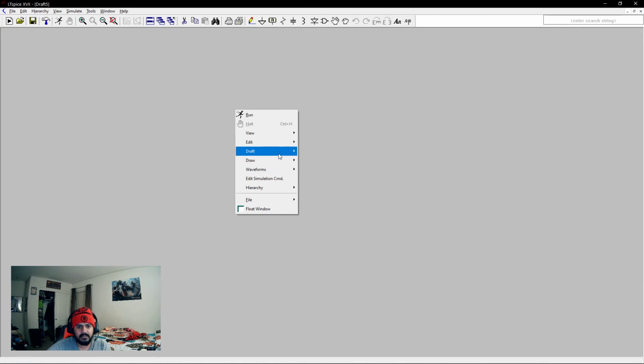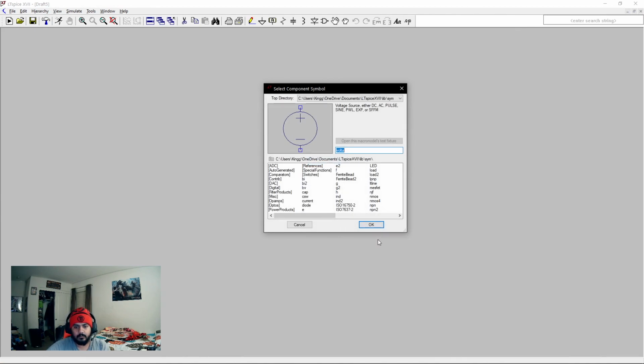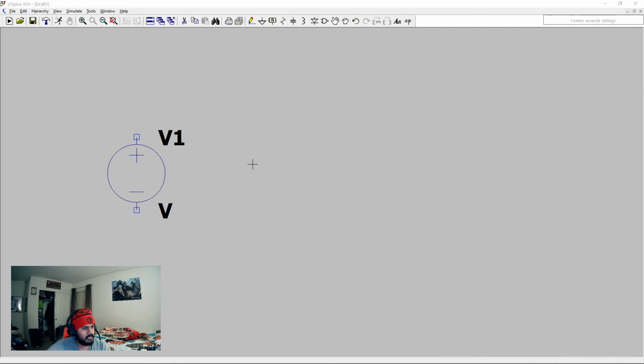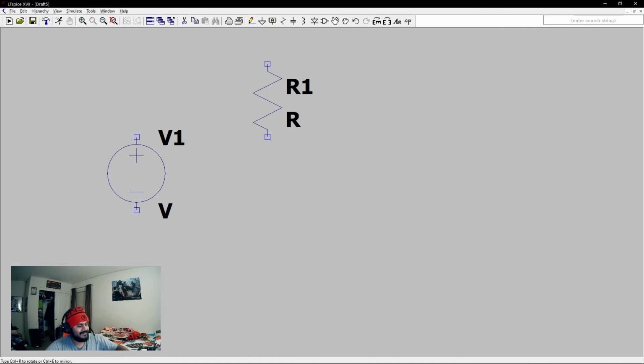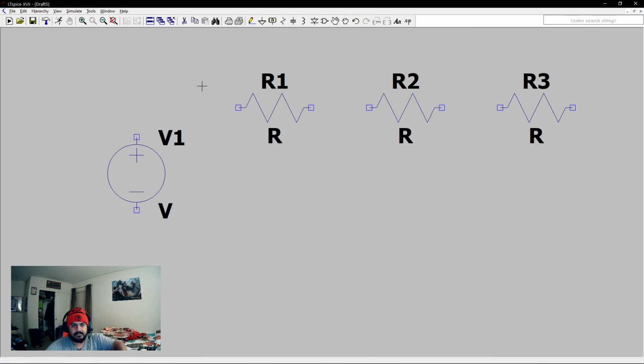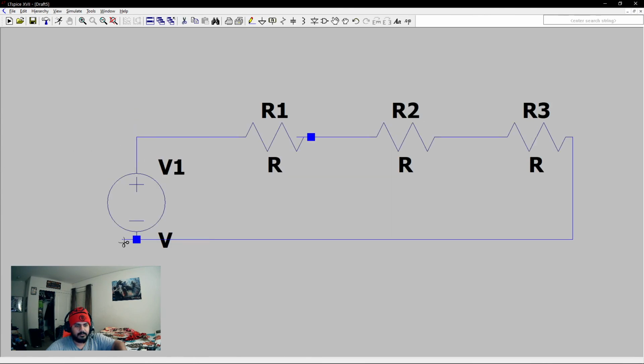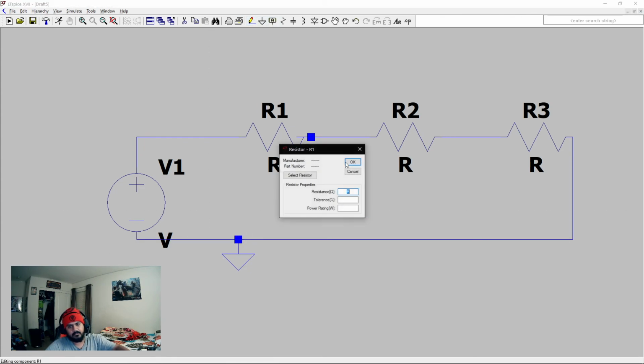For transient analysis, we're going to need a sinusoidal input. So we're still going to want to get the voltage source. So we plop in our voltage source, and let's make sure that we're using the same circuit. I didn't have to delete the previous circuit because we're using the same circuit again. I won't label the nodes this time, but you guys know where the nodes are. Just connect everything up again using a wire, add a ground, and then we'll label all these again.